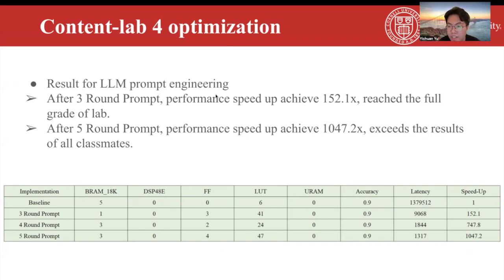First, we finalize the HLS optimizations. We ensure the LLM understood the baseline code and the HLS optimization techniques. The second step is to identify the bottlenecks. We target critical components like the convolutional layer and dense layer, which have the most potential space for improvement. Third, we use finalized prompt-based optimizations. Using GPT-4o, we finally refined the design through a multi-run prompt strategy.